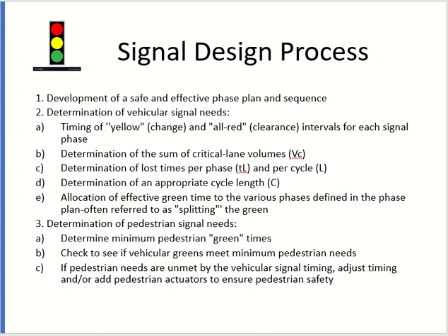Second step is designing the timing of the signal. The first timing we design is yellow and all red. Yellow is also called the change interval, and all red is also called the clearance interval. Which yellow? After the green, before the red.